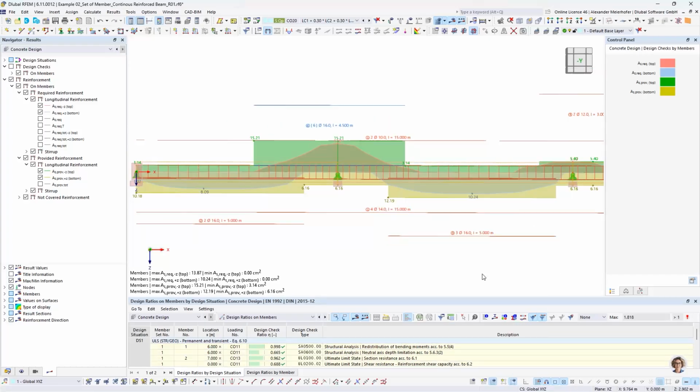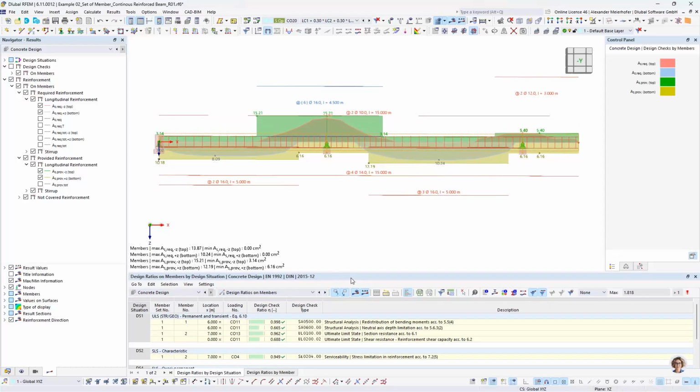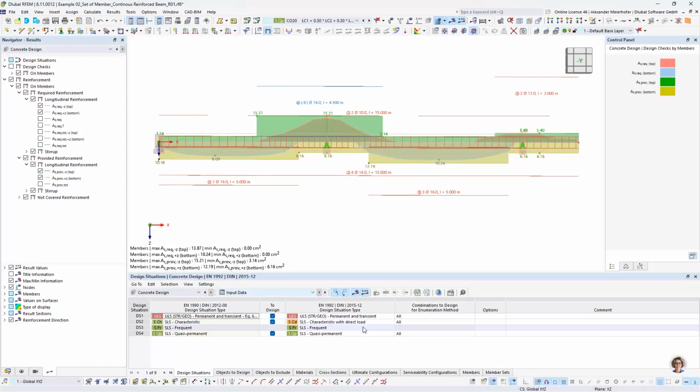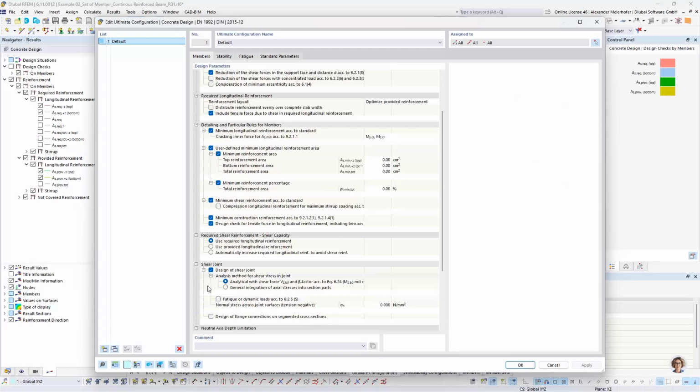one top feature for the beam design is that we can also use the net concrete cross-section area for highly reinforced sections. So this is also new, that you can remove the concrete area behind the rebars. If you have a very big reinforcement ratio in the cross-section, then you can deactivate in our configurations the area behind the rebars.